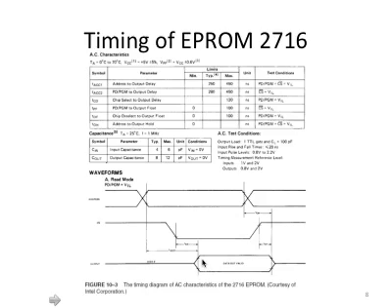select signal becomes 0 till you see a valid output on the data line, there is some delay. Okay? This is the delay by design coming from this chip, because the chip, the internal circuits, has to respond to all the control signals before the valid data can be sent out onto the data bus, onto the output. So this is the delay showing up here, TCO. This is the chip select to output delay.